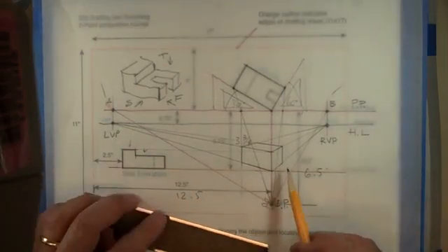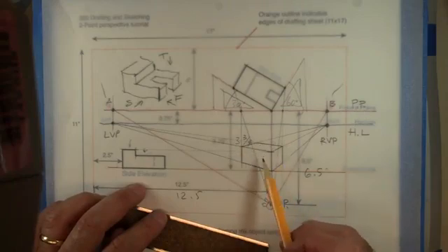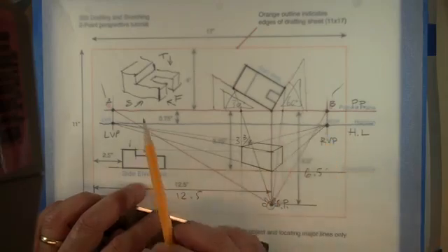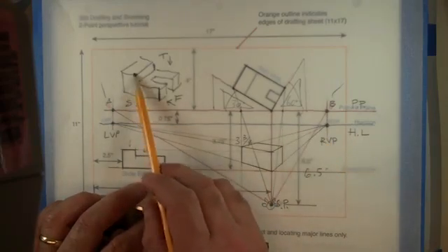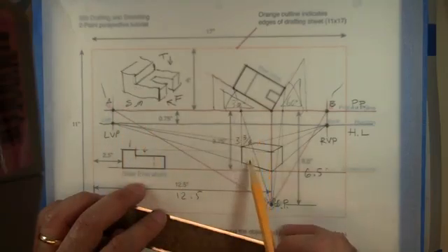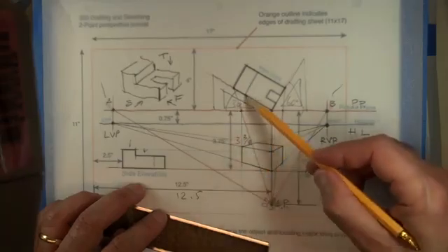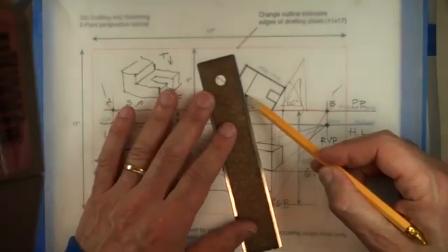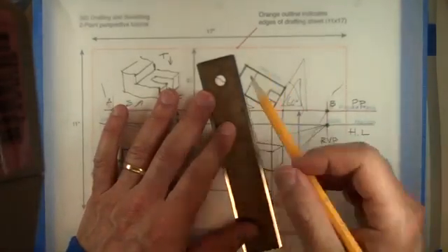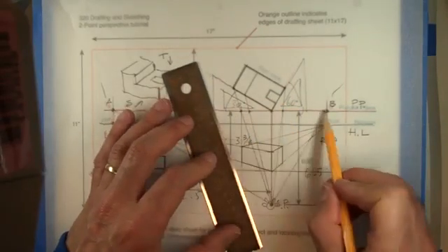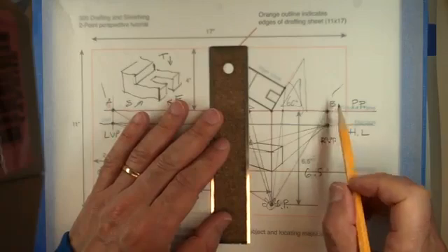Okay. The next thing we can try to figure out, now we have a lot of information, we won't need to construct every single line because the more we do, the less we have to do in a way. But let's figure out what this spot is, this line right here. So it's on the side of the object, and I can find out where it is by applying the same process to this point here in plain view. So I connect it to the station point, and where it meets my picture plane, I drop it down.